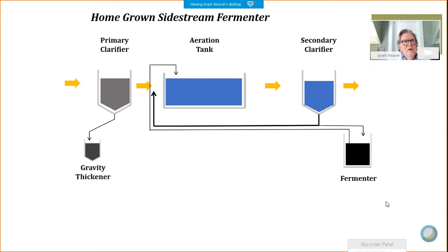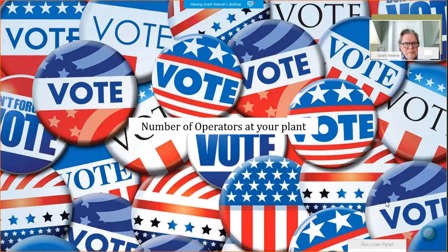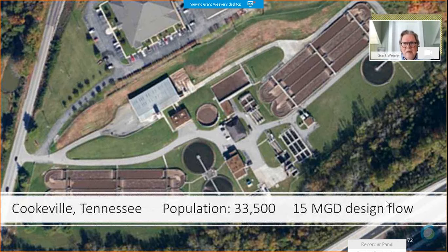The energized bugs that come back into that aeration tank, once they hit the aerobic conditions, should suck phosphorus out of solution. Of course, now you're adding some sludge back into the aeration tanks, so you're going to have to increase your wasting rate a little bit. Pretty good trick, and I'll give you some examples of where that worked in Tennessee. So unless there's any questions, let's get into the fun part.